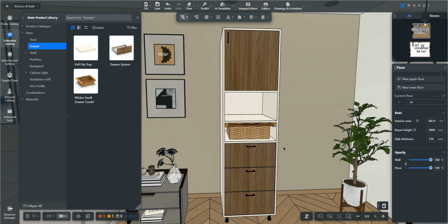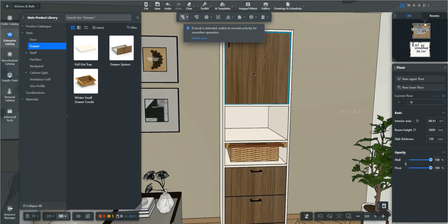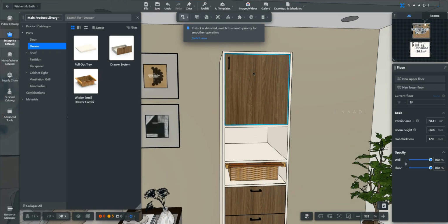on your requirement. And you should also notice that all this door and drawer, all this thing will literally behave like your conventional door or drawer, which means instead of the solid door, if I want to change this into a profile shutter, I can do that. Not only profile shutter, I can change any door style just like how you would usually change for your conventional cabinets. So in this case, if I want to change this door style, I can just select this cabinet.